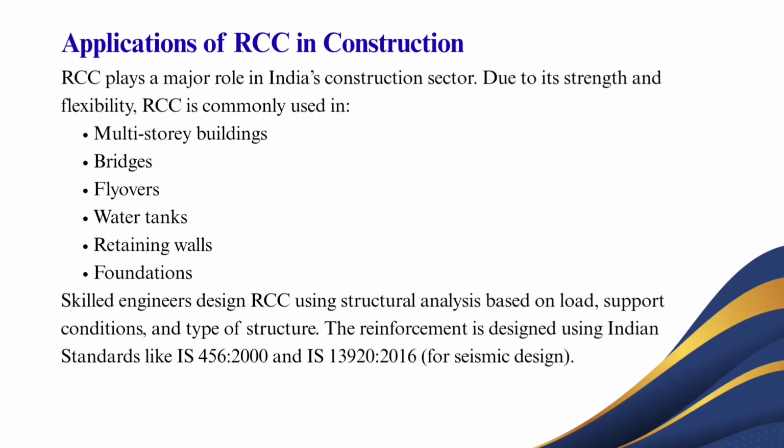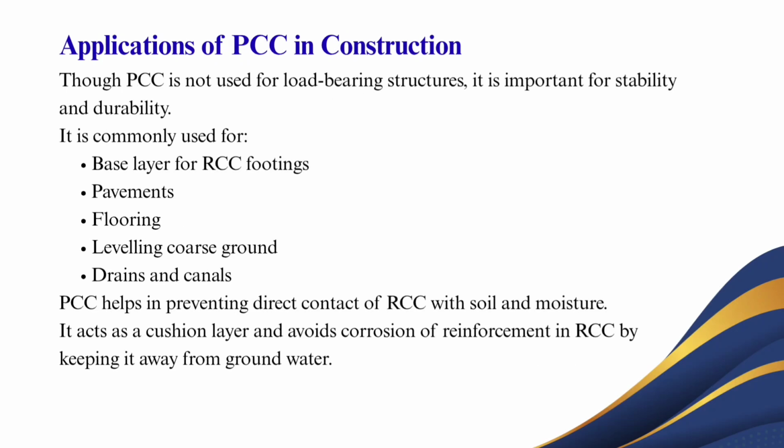Skilled engineers design RCC using structural analysis based on loads, support conditions and type of structures. The reinforcement is designed using Indian standards like IS 456-2000 and IS 13920-2016 for seismic design. Now the next point is applications of PCC in construction.